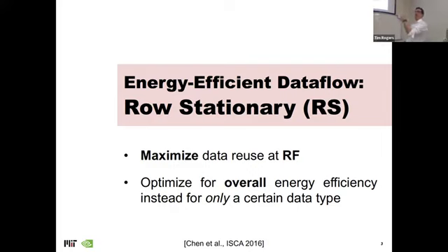And again, the name of the game here is not necessarily raw performance. The name of the game is energy efficiency, which could translate into raw performance, because if you're more energy efficient, you can put down more processing elements for the same power budget. This work has a flavor very different from a 565 thing, like a branch predictor or a prefetcher, where you're just trying to reduce the number of cycles. Here, we're trying to reduce the energy such that you can scale up the hardware to get more performance. So it's a fundamentally different way of approaching things than we've done in traditional architecture.